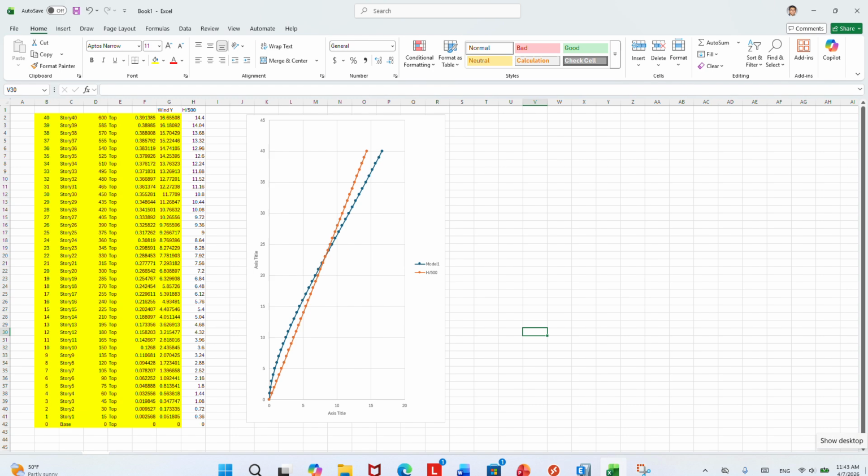Now, which area is better to stiffen up, which is more efficient? Because 24 inches, 22 inches, 20 inches, right? So what thickness am I choosing? So do we want to continuously increase the wall thickness or now adopt a new feature, outrigger, right?